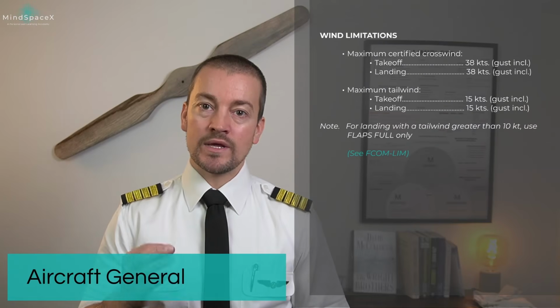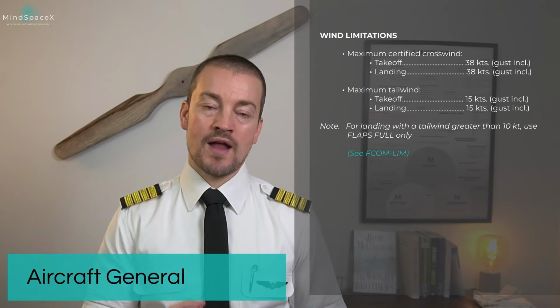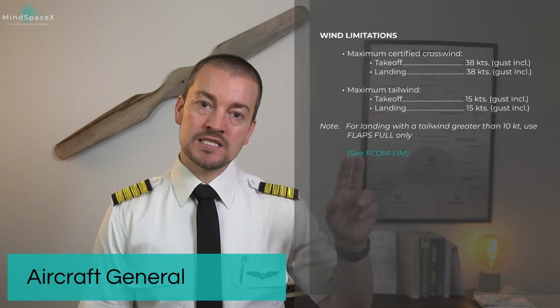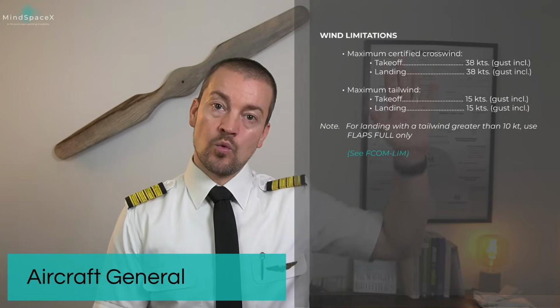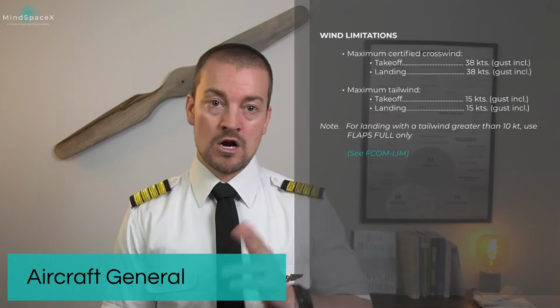For landing with tailwind greater than 10 knots, we should use flaps full only. Always refer to the FCOM limitations chapter for wind limitations, as they can be specific for your model of aircraft.